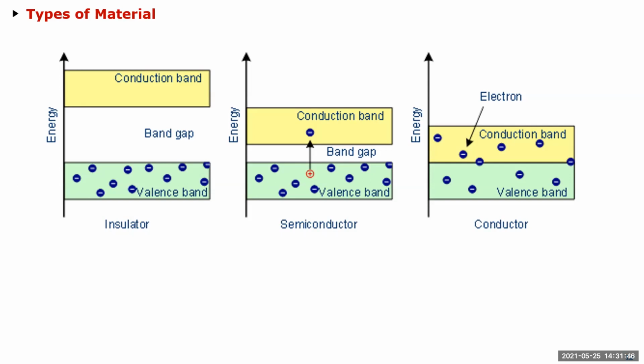You come to 0.18, it's scaled almost like 5 times. Not 5 times, maybe less than that, because they do a lot of process engineering. So in 0.18, the usual voltage is 1.8 volts. The breakdown voltage is around 2 to 2.2 volts. So you apply 2.2 volts, then the oxide will break down and your chip is no good anymore. So just remember that. So usually there is no conduction.